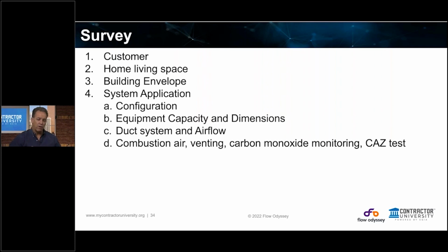Anyway, you need to walk around the living space and test for this with a low-level carbon monoxide monitor. And then I talk about how, even though you're putting in good equipment and doing it the right way, that doesn't mean they still shouldn't have some measure, just in case something were to happen, right? An ounce of protection. Yeah, I like using low level. Whose do you use, CO Experts or NCI? I'll use both. There's actually 6 manufacturers. Okay. And they're using the same sensor in every one.